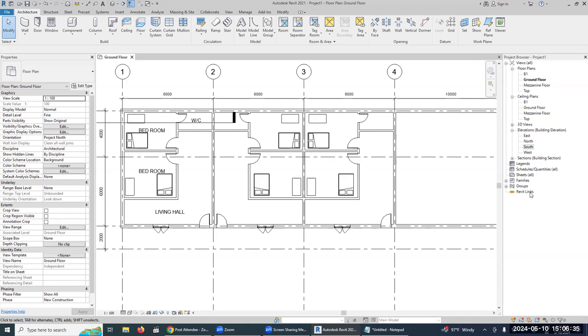What happened? Select again, select it. Okay, go to filter, remove room tag and room. Say okay now. Okay, hold the shift key and click on the wall and this wall also. Now mirror. Click on the middle line and one more time click it here.